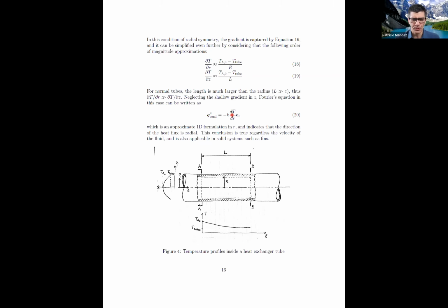And this would apply. This is an approximation, it's not exact, but it's an approximation that is so good, we're going to be doing it all the time. For those of you in MATI, when we do calculations about welding, the plate is much broader than it is thick. So we apply this condition, and we consider the heat losses are all in the radial direction and not longitudinal. Very interesting. If you take the heat transfer welding class, you're going to see more about that.